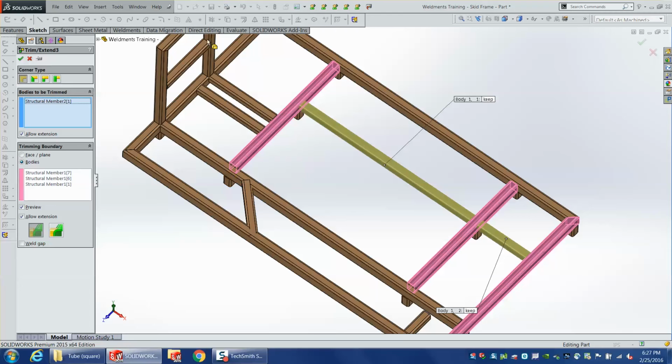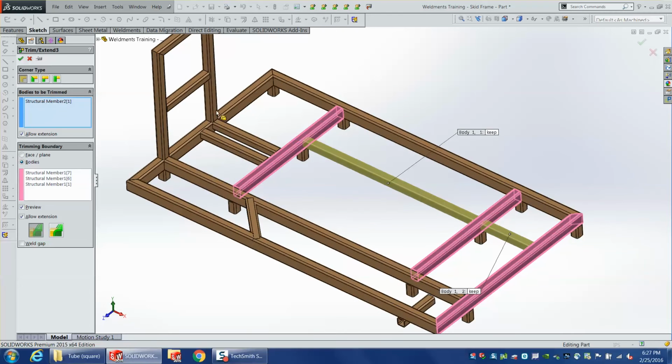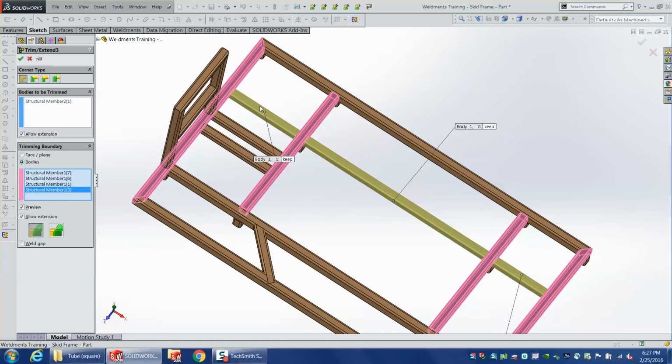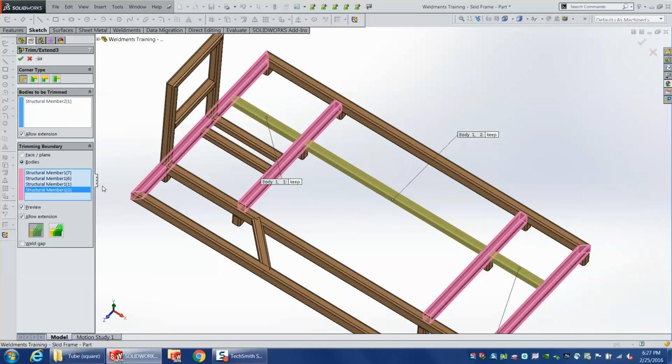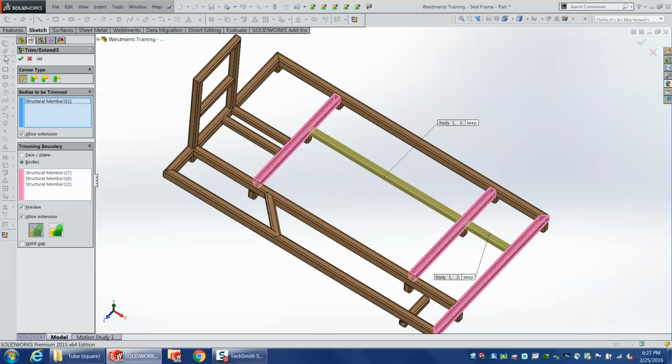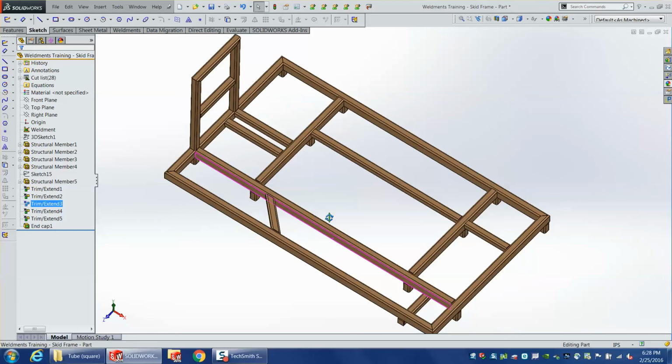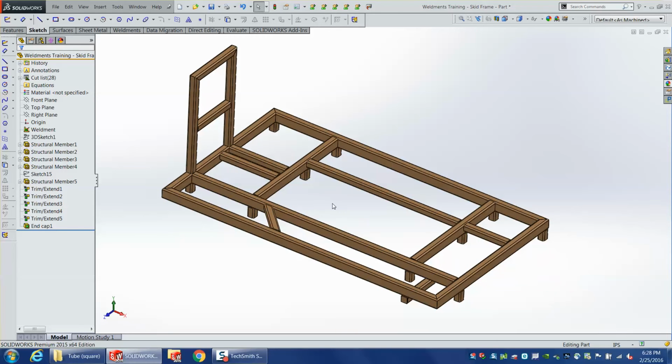If you get into more, if you're trying to add too much there, then it starts extending your other beams along with it, which wasn't what I intended to do. So that's just a general rule. You'll obviously break it at times, but it helps keep things simple and organized that way. Think of one beam, what's the stuff I'm going to trim with it, or one plane, what's the stuff I'm going to trim with it.